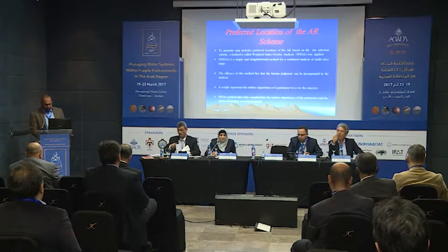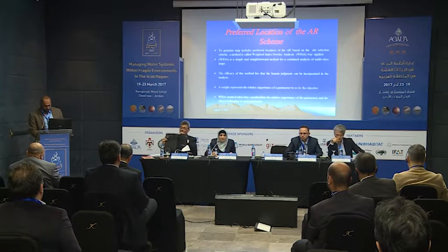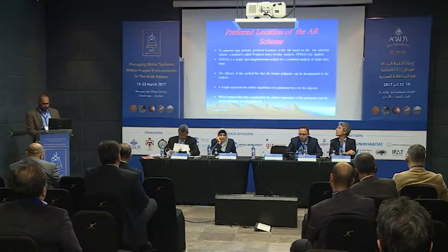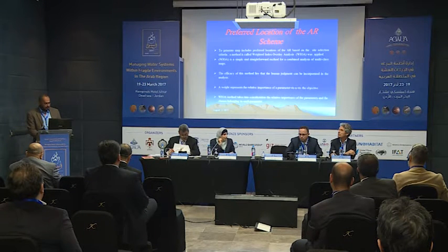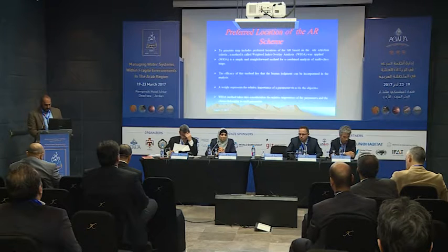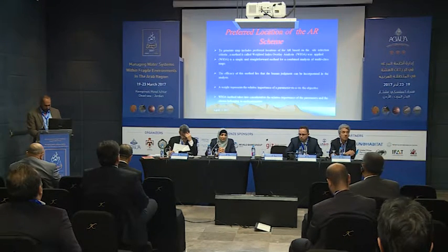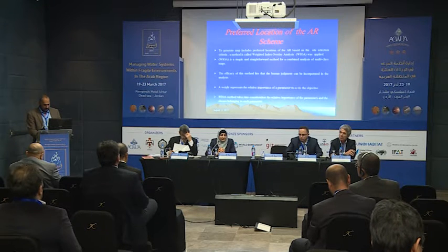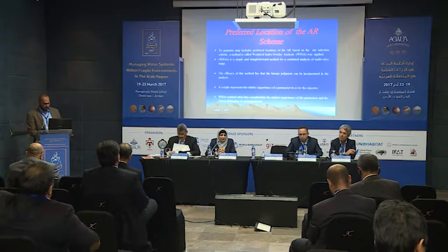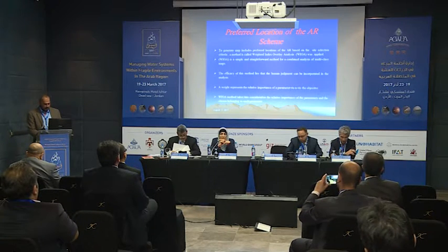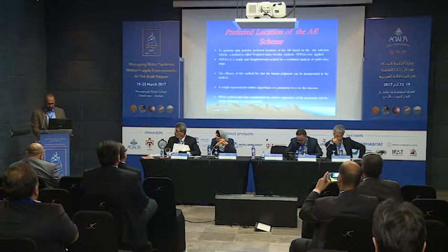To go directly to the preferred location of the artificial recharge, we developed a method called weighted index overlay analysis. This is a simple and straightforward method for a combined analysis of multi-class maps. This method uses the maps for the previously mentioned criteria, and to apply it we give a weight value for each raster map. This value can be given according to human judgment. This weight represents the relative importance of the parameter vis-a-vis the objective, which is artificial recharge.